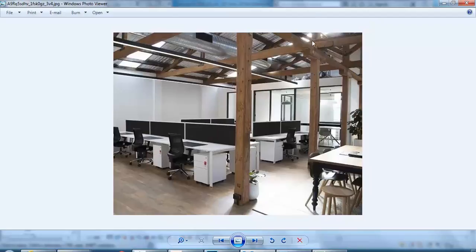And that's why they've got this, what is it, a newel post, I think, the one that goes up in the middle. And that's often a sign of a roof structure that looks like a truss, but actually isn't functioning as a truss. So a true truss spans all the way across the distance of the chord, or the piece at the bottom, and forms a single structural element. And in this case, it's not a single structure because it can't function without those columns there to support it. So we need to put the columns in.